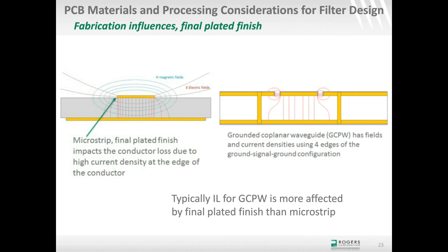We've done a lot of studies on this topic as well, and there's a couple of things I wanted to point out. Again, being that a lot of filters have edge-coupled features, I wanted to talk about that and make everyone aware that edge-coupled features usually have more losses and are impacted more by the final plated finish than a single-ended transmission line like a microstrip.